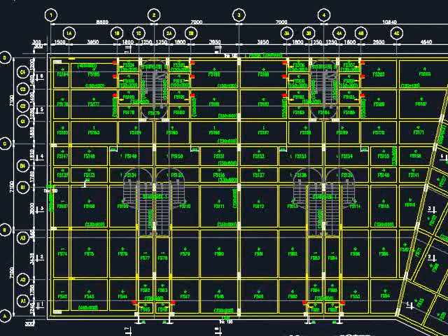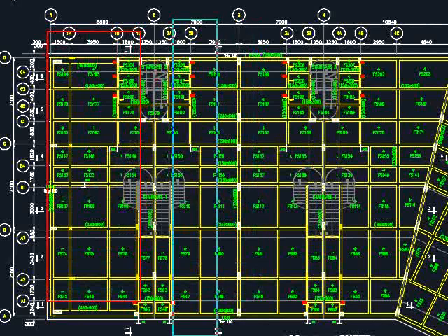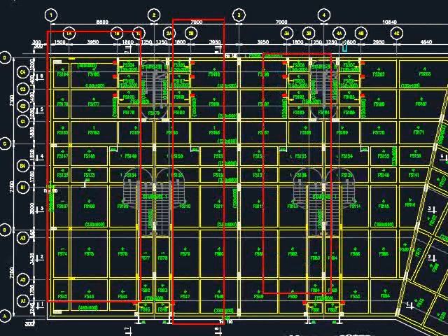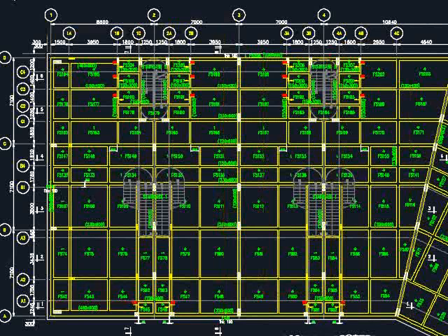For example, in this structural key plan, you have 1, 2, 3, 4 units of the buildings, and this building is symmetrical along the length here. That means the other 4 units will be mirrored along this length. Now you need to decide which cross sections you would like to indicate to be shown to the contractors so that they know how they're going to produce the slabs.